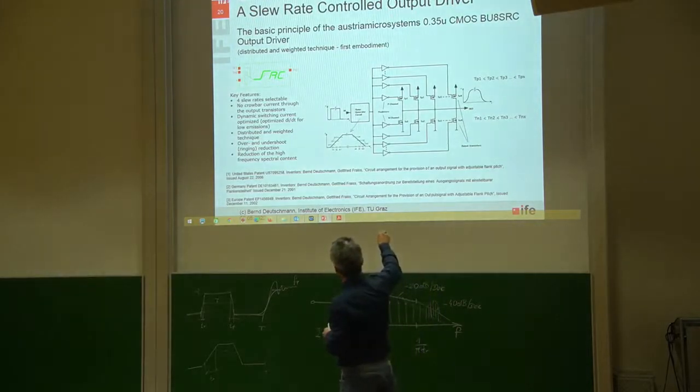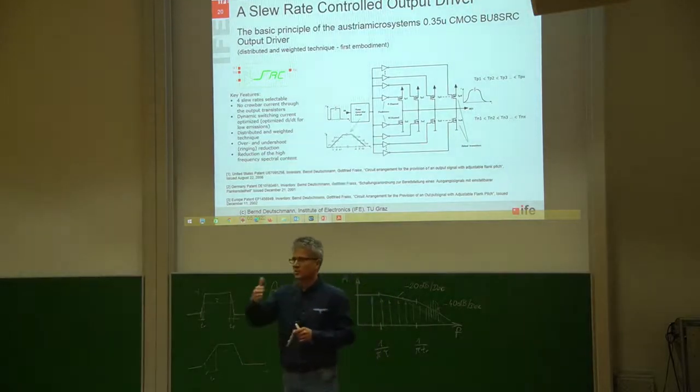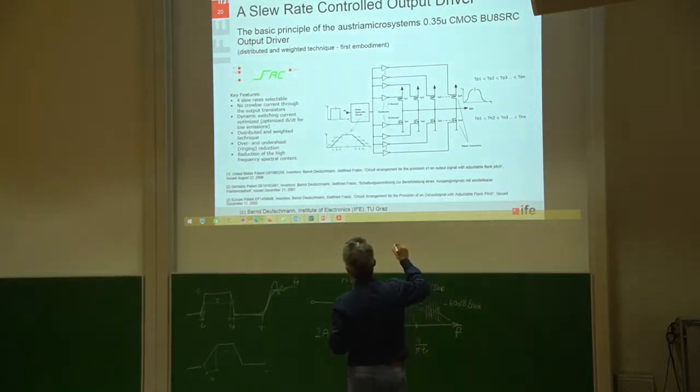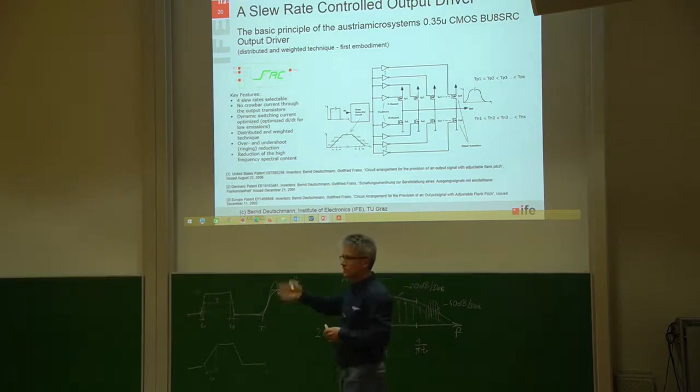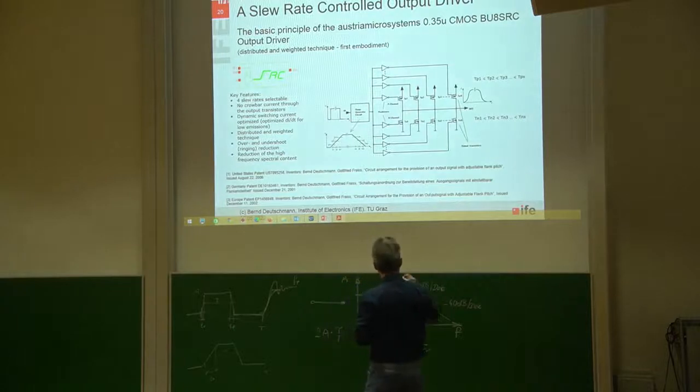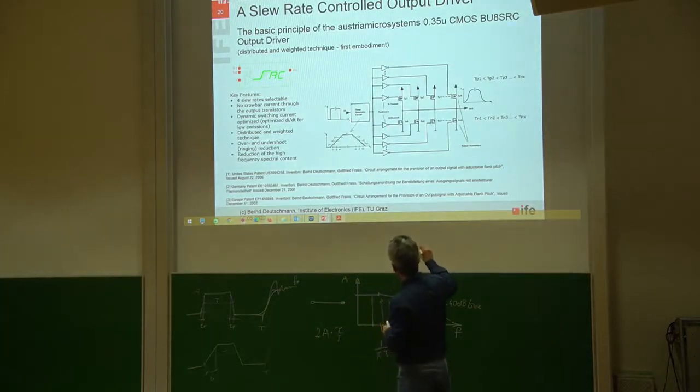So the ramp generating circuitry was then directly driven by the signal coming out from the core logic. So it was a rectangular signal in order to turn the outputs on, for example. And what this ramp generation circuitry does, it was ramping up this output signal with a certain rate. And all these pre-drivers are designed in a way that this one turns on first, then this one as the second, third, and so on until the last pre-driver is turned on.